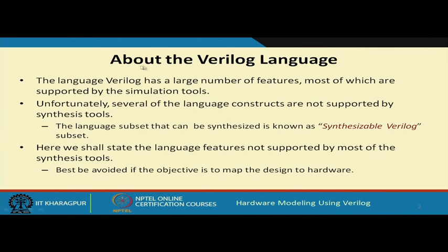So, the Verilog language provides you with a number of facilities and features, and these features are mostly supported by the simulation tool. For example, the simulation tool that we have been using as part of this course, iVerilog, and of course the waveform viewer GTKWave, are known to support most of the Verilog constructs that we have been discussing throughout the class.